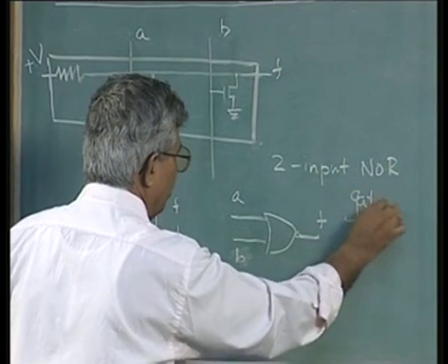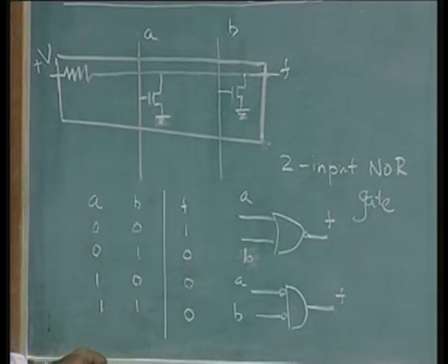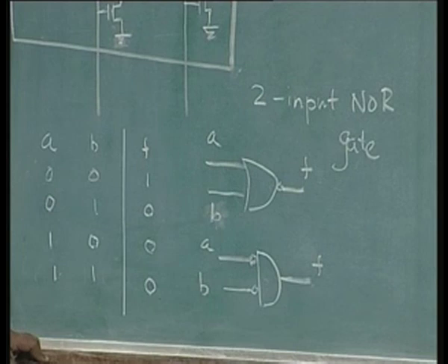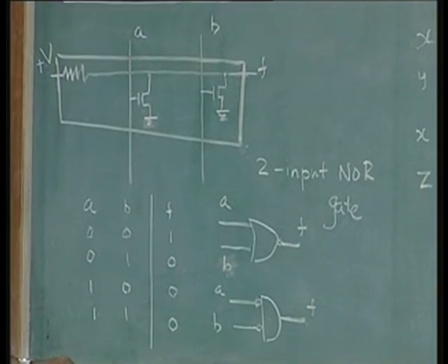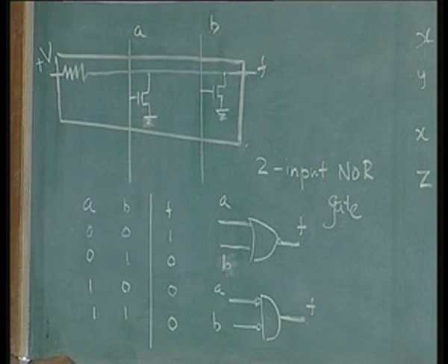I said in the programmable logic array device, all the gates inside are NOR gates, even though we may have an AND array and an OR array. Of course, inverters, you know that NOR can be converted to an inverter, NAND can be converted to an inverter. We know all that from our previous course on digital design. So now I have to tell you how I can get whatever function I want for F1, F2, F3, whatever, using the inputs A, B, C, etc., using only a complete NOR gate combination.